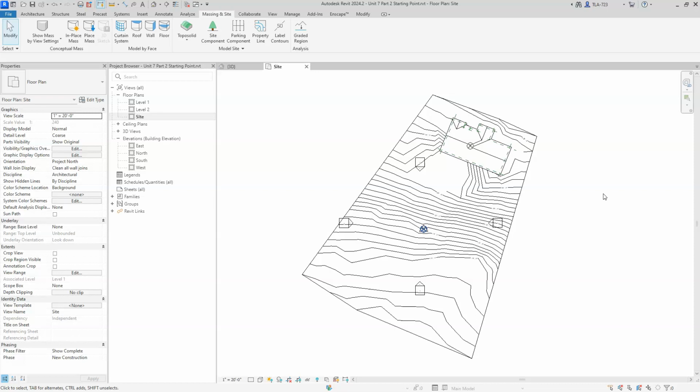The exact location of the corners of a property are so well documented in a legal document that when you have to draw one, you really need to know exactly the direction and the length of all of the legs of that property boundary. Now that might be data that you've collected during surveying, or it might be data that you received from somebody. But if you ever have to reproduce it in Revit, you should be doing that according to the exact measurements and angles, so distance and angles of that property boundary.